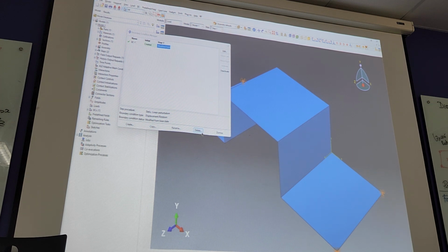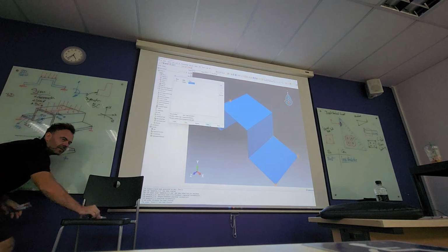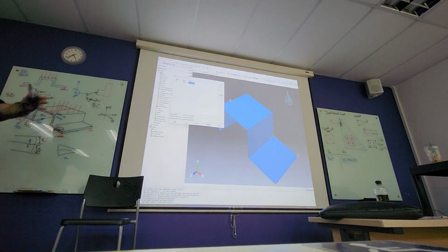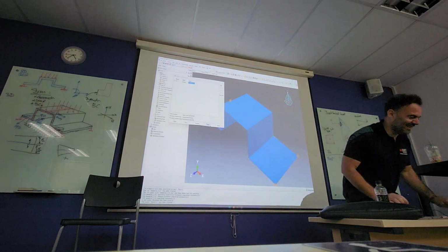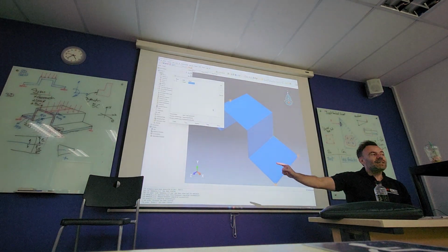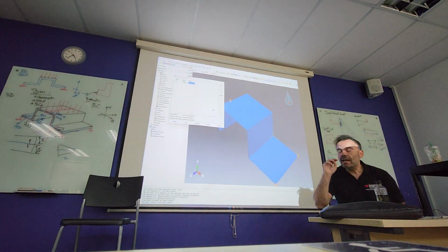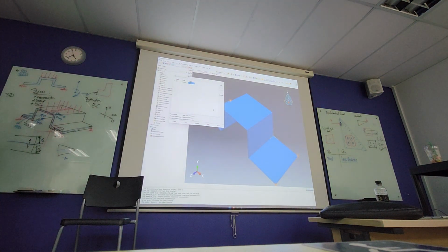What's the roller stopping us from doing? Up and down. To lift off. Y is locked. So it's only one that is locked, and X and Z are free. Yeah. So it's free to roll, basically to do this, but I can't do this. I can sort of roll, like when you've got roller blades, you can fly as well, but most of the time you're just rolling, yeah? So had it been a roller, you only lock one, which is vertical. It's not always vertical, it's always perpendicular. Remember that